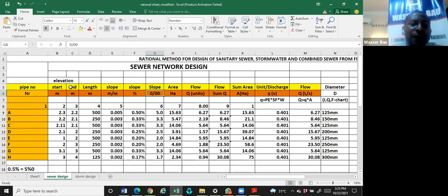So now I have written the pipe sizes, I have written their lengths, their slope becomes the vertical height over the horizontal length, which is the gradient. Somebody called it gradient yesterday. So the gradient will give you this. Then if you multiply by 1,000, it will give you per thousand or per mil. Engineer Eddie and John, do you have a question?